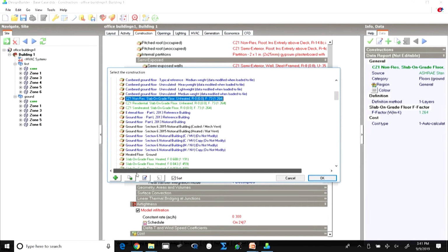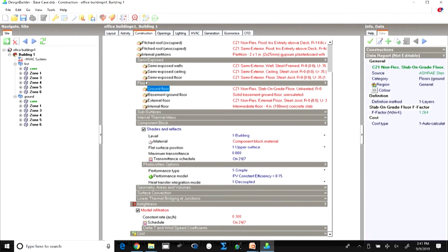For greener constructions where we are deliberately selecting materials which are environment friendly or which have a higher thermal mass or act as heat sink, we may select these different materials for the ground floor and also the internal partitions.